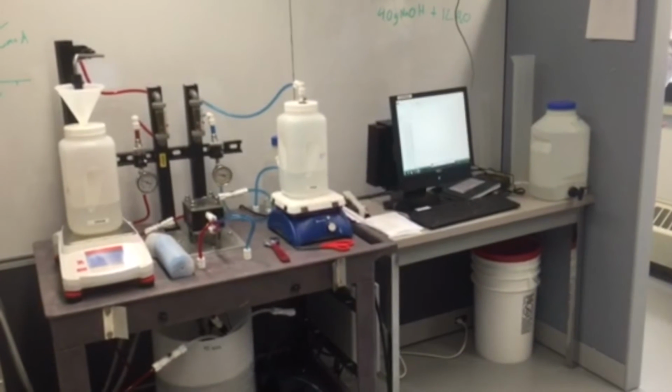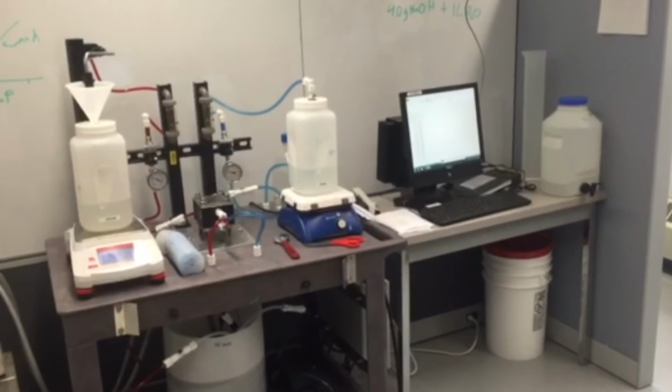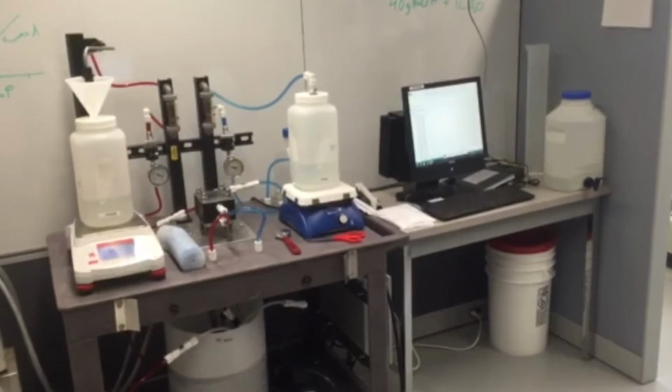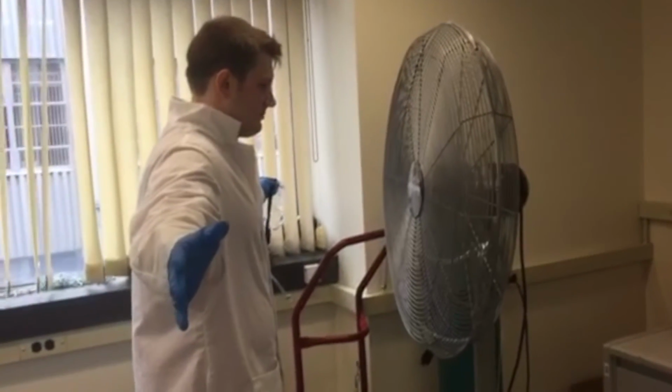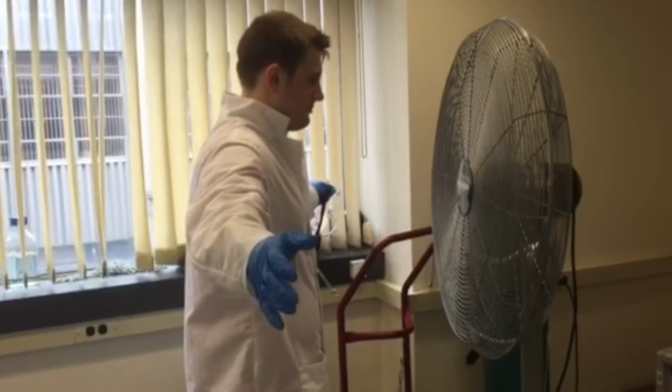Drain each tank into the sink and refill with 2 liters tap water. Flush the system for 5 minutes and then repeat with 2 liters of tap water. Flush a third time with 2 liters of distilled water. Use a compressed air line to purge the system. Open the cell and dispose of the membrane. Repeat all steps again by changing the pressure to 6 psi and then to 8 psi.